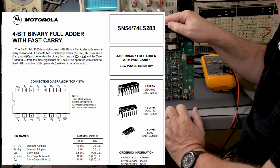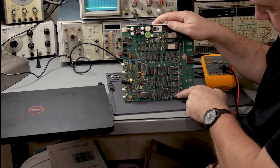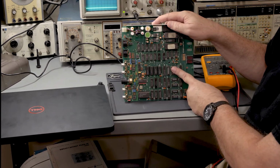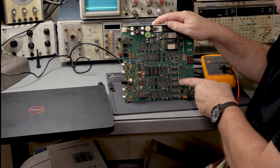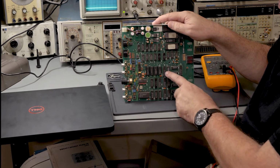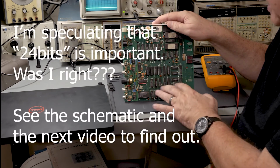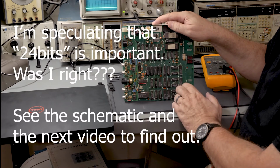So, what are we adding? Well, since they're 4 bits, I can say that's 8 bits, that's 8 bits, that's 8 bits. That's 24 bits. And that corresponds to 3 8-bit parts here. And these 3 8-bit parts here, you can see these are latches. So again, 24. We've got a 24-bit adder hooked to 24-bit registers.